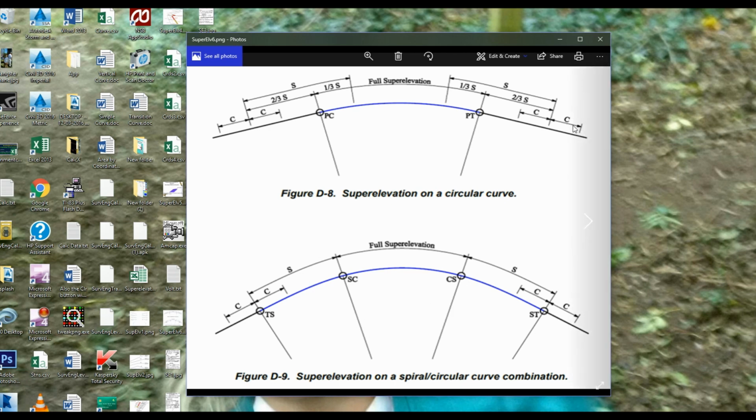Now for continuous crown, it's dead easy because all we need to do is use the same 11.077, and we can subtract that on this side of it from the runoff to give us the continuous crown there. It's the same distance, and similarly on this side there, we just add that to the runoff 2/3 value there, and that would give us the continuous crown there because those are both the same.